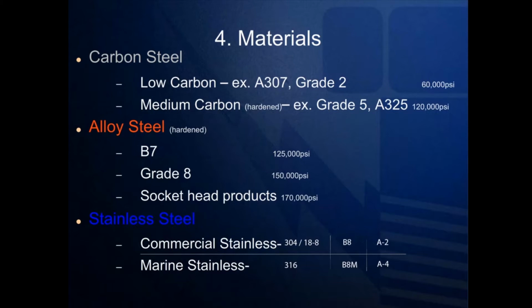Alloy steels are broken into two different groups, low alloy steels and high alloy steels. The difference between the two is somewhat arbitrary, but many define it as 8%. Most commonly, the phrase alloy steel refers to low alloy steel. Technically, every steel is an alloy, but not all steels are called alloy steels.